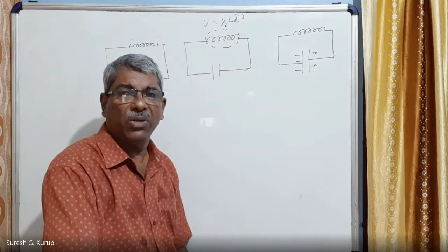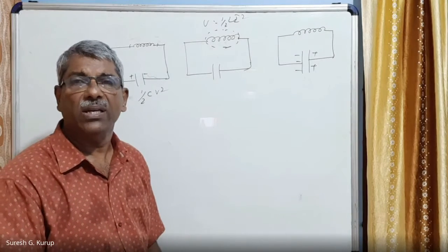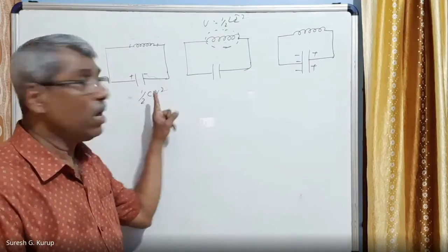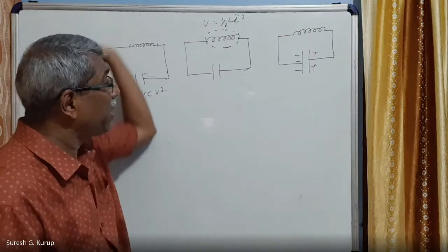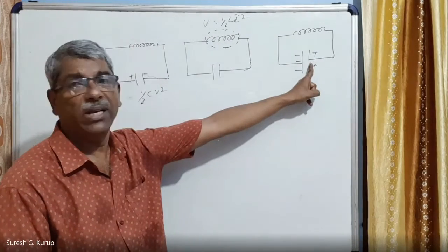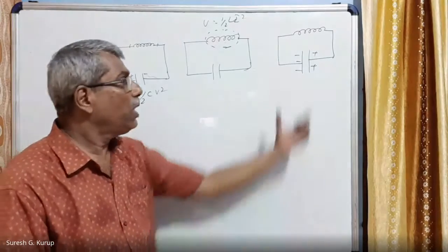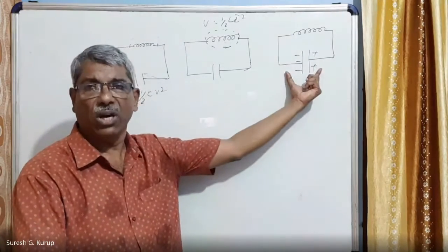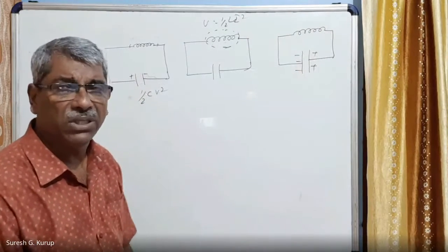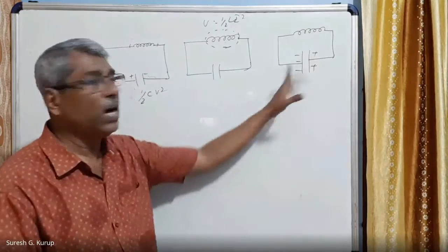Right? Because this is an oscillatory circuit, and an oscillator circuit is a circuit that can convert DC current to AC current. So this is the first half. In the first half cycle, all the positive charge of one plate has gone to the second plate. So now this is positive and this is negative. Now again the capacitor is fully charged and the magnetic field inside the coil is totally empty. Energy is changed from half Li² to half CV².